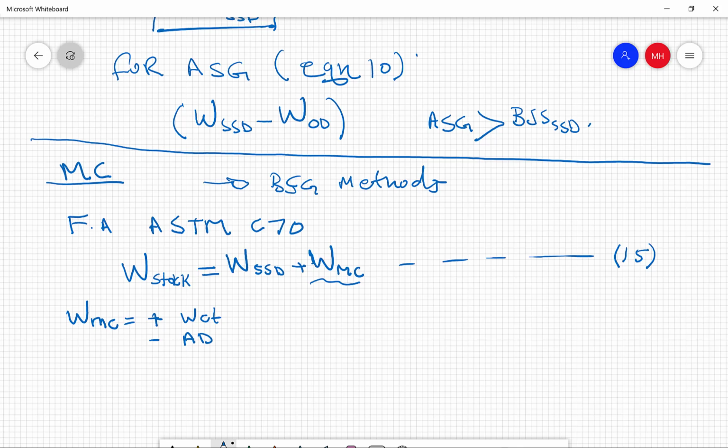So the usual measurements are then made as if the bulk specific gravity of the aggregate was to be determined. So it is assumed that the aggregate reaches the SSD condition during measurement.